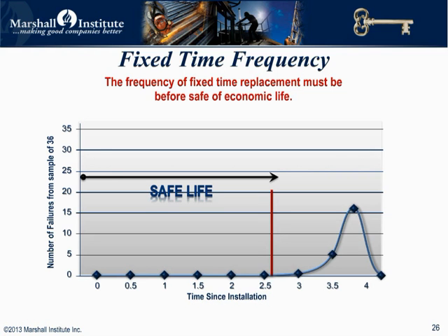Timing chains on auto engines may be a really good example of this type of failure characteristic. The Toyota Camry required the timing chain to be replaced at 90,000 miles, not more. I was told that it might go further than that, but anything beyond that was taking a pretty big risk. If the chain actually failed, it would cause catastrophic damage to the engine. The chain replacement, though not cheap, was far preferable to the consequential repair if it failed.